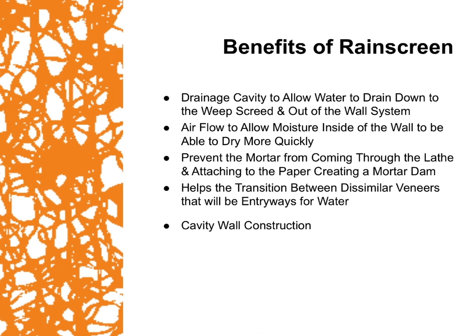Now that we're getting more energy efficient and greener and making buildings tighter, it's a cause and effect. By taking away that energy movement through the wall system, you are making it harder for our walls to get dry. Without airflow, that moisture stays behind our facades, and all it has is time. Moisture and water will wait and wait as long as it needs to, taking advantage of the system and tearing away at our structures drop by drop.